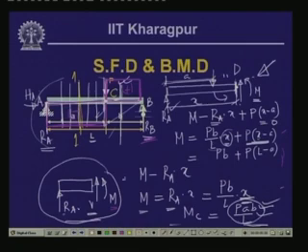So the value of the bending moment which we are getting at this particular point is M minus R A into x plus, again in the same direction, P into x minus a. So this is going to be minus P b by L into x minus P into x minus a. And L minus a is nothing but b, so this is equal to 0.